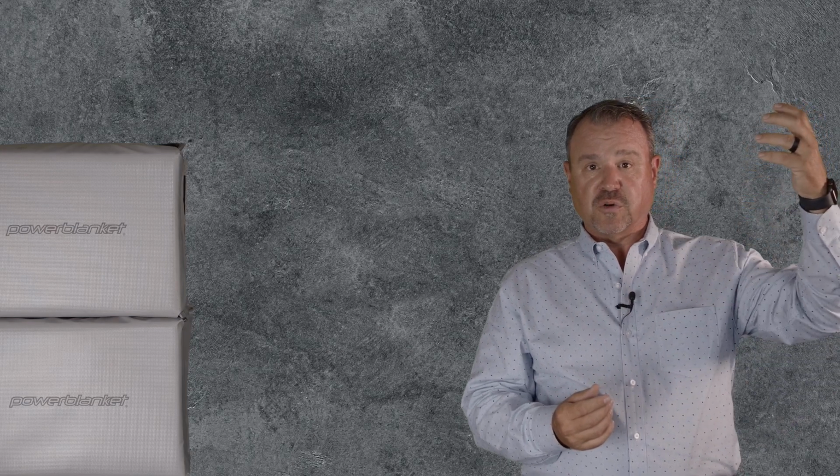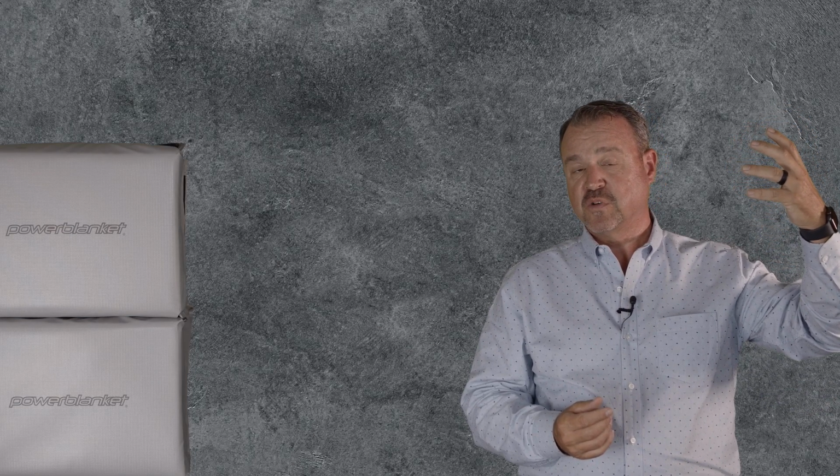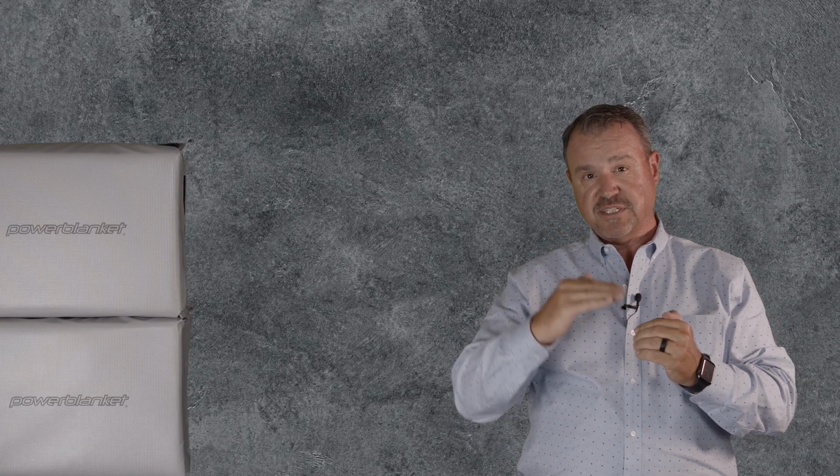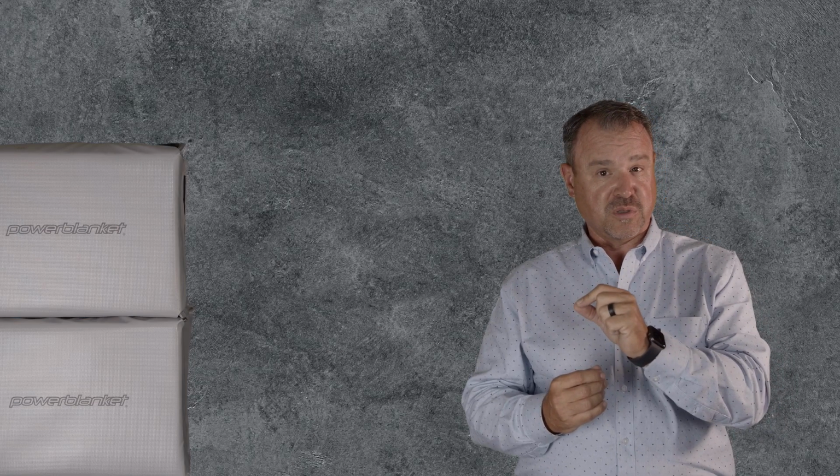So if you have a controller that's capable of sensing your process and asking for changes multiple times in 1 second, an SCR can handle the job because it can change the output to the heater rapidly and accurately. So if you need precise temperature control or a more efficient use of your electric power, an SCR power controller is a very easy upgrade in a system that needs to be accurate.